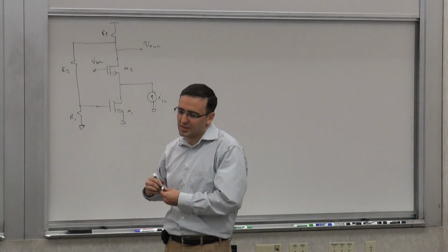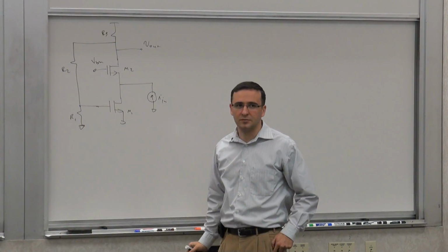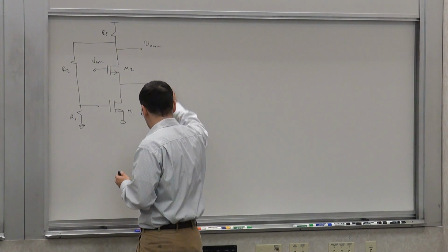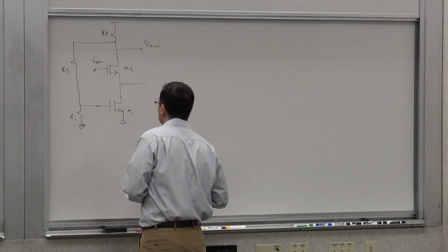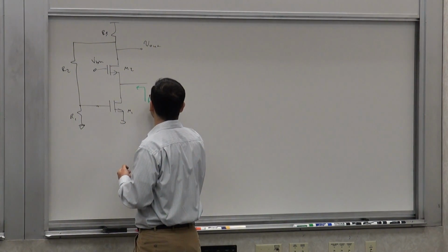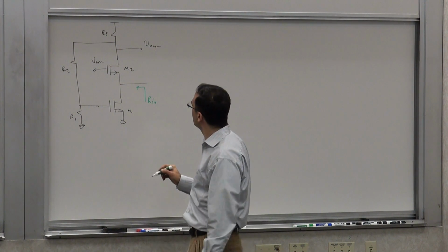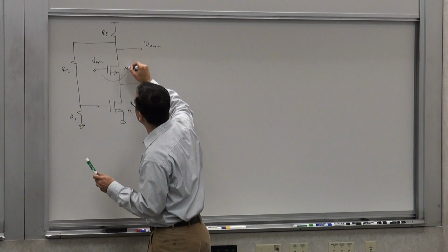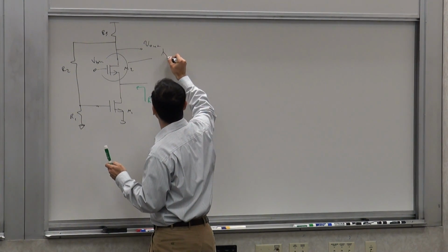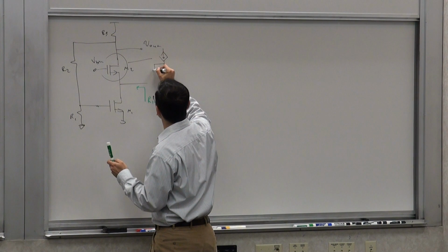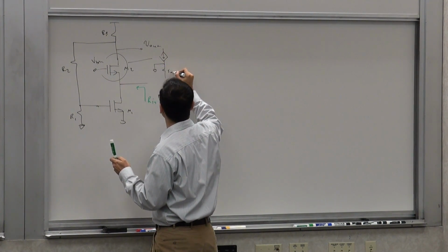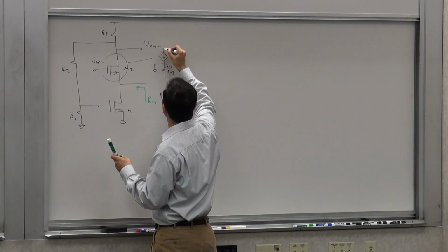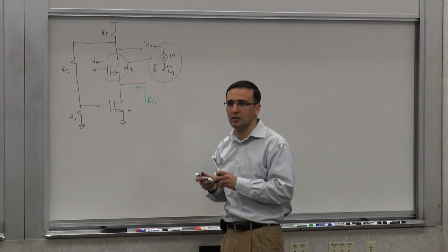Okay, so let's say I'm interested in the impedance of this node, the input node first. Right? So I'm interested in Z in, or R in this case. So what do I need to determine? Which one was my source? We chose this source, so we'll keep it consistent. Remember, we had the T model here, this ground at RM1 or RM2. This is IS2. Right? So this is what it is.